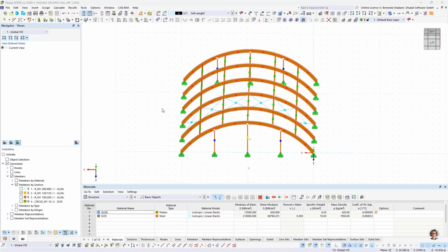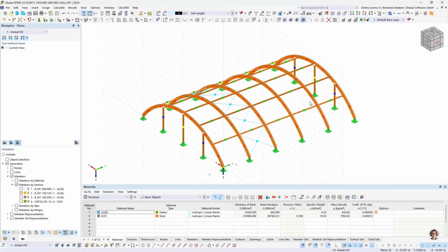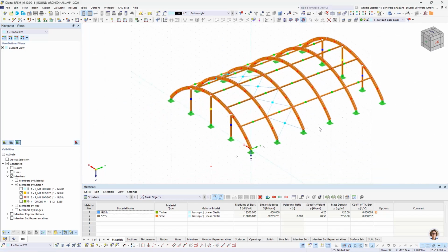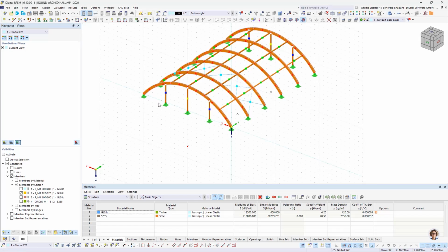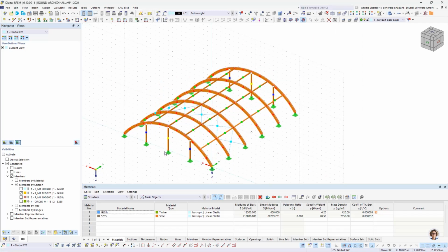Now we come to the second part of our webinar, which is also the last input. To proceed with that, I will firstly need to model at the gable supports 2 load transfer areas, which will help with the load transfer. They are probably the biggest advantage that we have today in RFEM 6 and that we also use in our model.